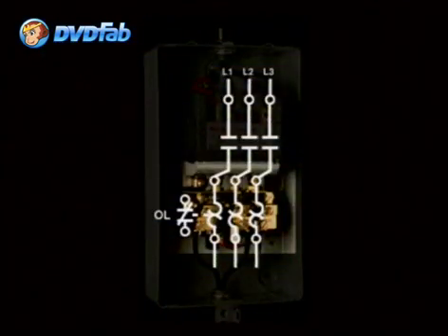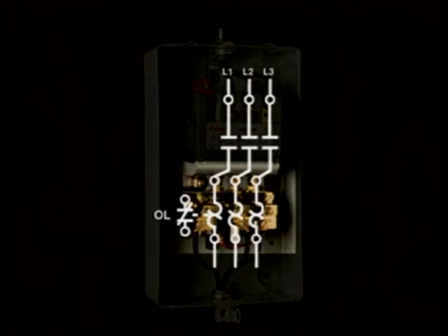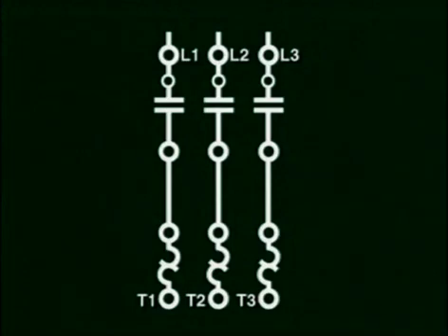As we mentioned, the wiring diagram illustrates as close as possible the location of the wiring connections. In this starter, for example, you will find a wiring diagram like this, which shows all the connections to the starter, in addition to the location of the components within the starter. The symbols in the wiring diagram show the location of these components in the same manner where you would find them if you were looking at the starter from top to bottom.